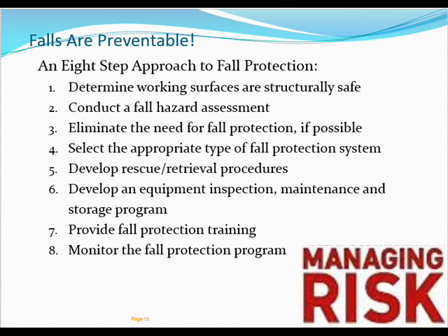Falls are preventable. An 8-step approach to fall protection. 1. Determine the work surfaces are structured safely. 2. Conduct a fall hazard assessment. 3. Eliminate the need for fall protection if possible. 4. Select the appropriate type of fall protection system.